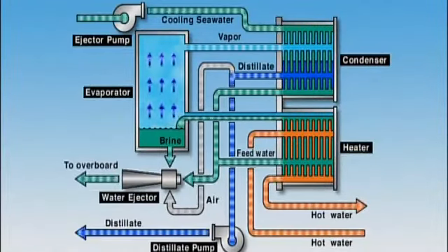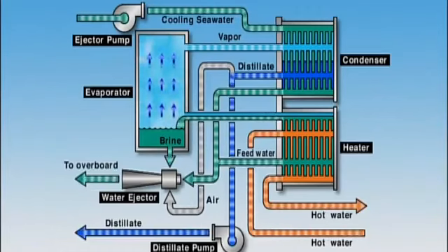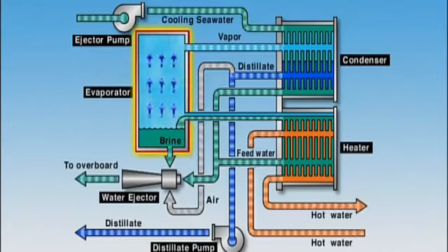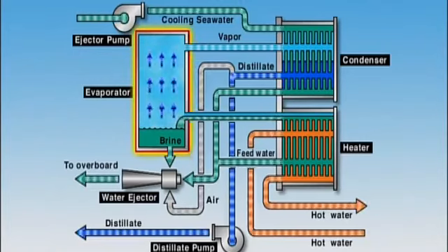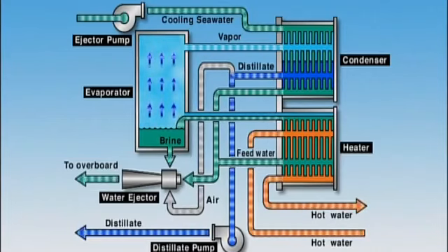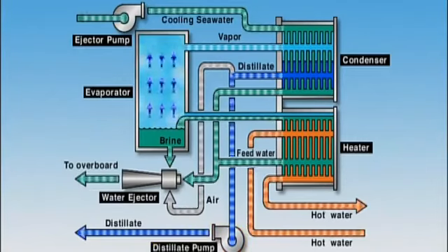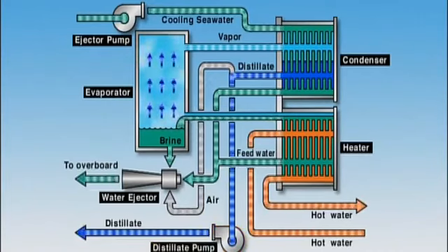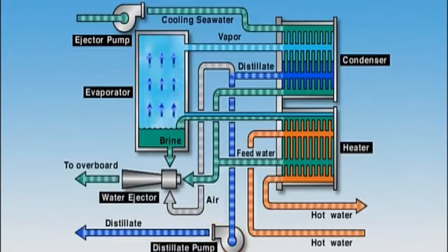The vacuum evaporation plate type distilling plant produces distilled water by evaporating seawater via low temperature evaporation under an internal vacuum, and then cooling and condensing the resulting vapor. This type of distilling plant is found on many ocean-going ships. Fresh water produced with this type of plant has a low salinity concentration, usually 5 ppm or less, so it can be used for a variety of purposes, including boiler water, operating water for machinery and equipment, and domestic water.